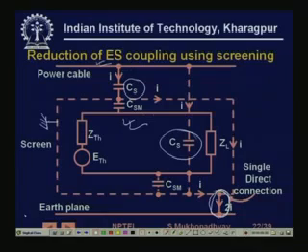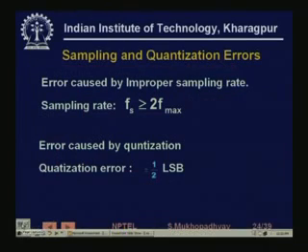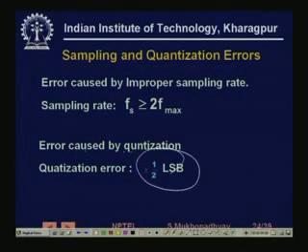So you can easily obtain a very high number of samples, and secondly the number of bits used in processing is also becoming quite large. The quantization error, which is typically limited to the plus minus half LSB specification, arises because of quantization.